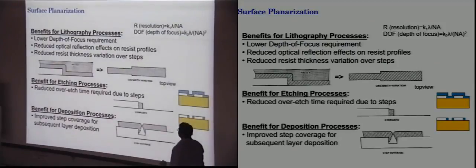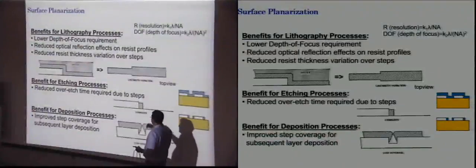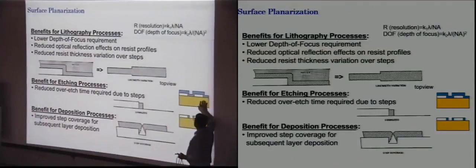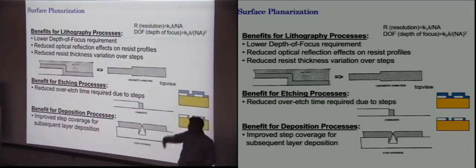Okay. The second problem is in the etching part. So this is shown more clearly over here. So let's say you have this metal, let's say you have this SiO2 layer over here, and on top of that, the blue thing is a silicon nitride layer that you have grown. Now when you do an etching, physical etching where it is cutting from the top, on the top it is gone, on the top it is gone, but at these edges, these materials will still remain. This can be silicon nitride, this can be photoresist. Because your etching is vertically down, you could have these kind of stringers being created.